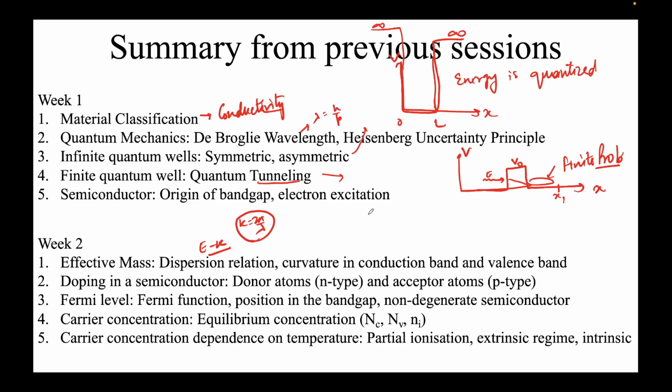And we saw that indeed when you apply all these quantum mechanical principles, what we could see is that in some materials this band is filled and the electrons can reside above EC, this is the conduction band, below EV, which is the valence band, this is the forbidden gap. I'm drawing it flat. It was actually not flat, it had curvature.